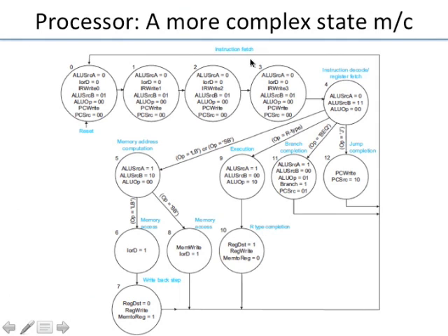Every microprocessor, any microprocessor, will fetch an instruction, it will decode the instruction, and the instruction might ask you to do some operation on some data items. So it will have to fetch the data items, do the operation, take the result and put it back in some place. Okay, and then that is basically the cycle it keeps on doing. Right? You power it on, you reset, you let it go, it just keeps on doing that. Fetch, decode, execute, write, fetch, decode, execute, write, and so on.